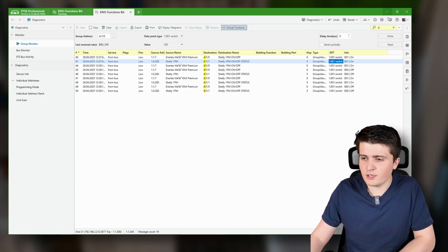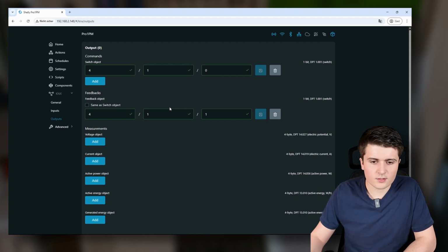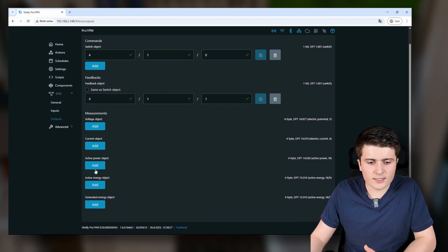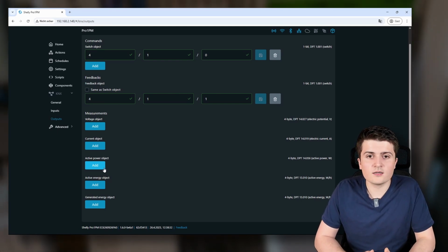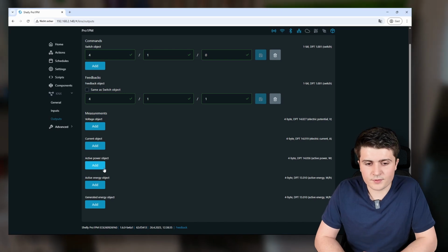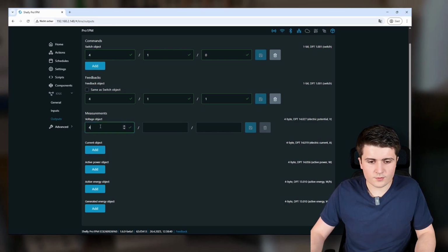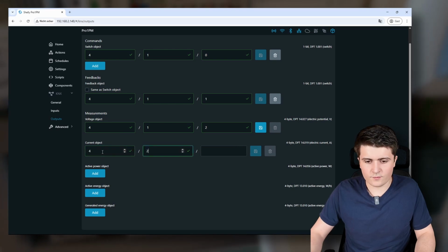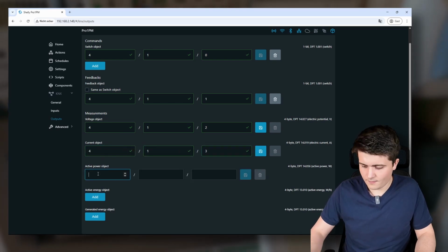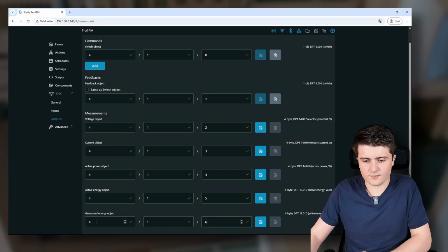But that's not the only thing the KNX integration in the Shelly device can do. So what else can we do? Well, here we can also set up group communication or group objects for the power measurement. So here we can enable objects, for example, for the voltage. So let's set it to 412, 413, 414, 415, and last but not least also 416.